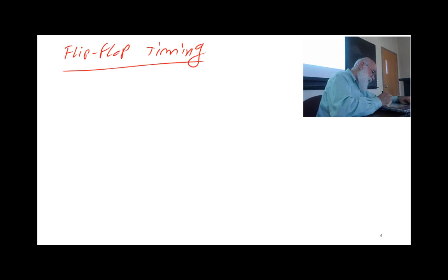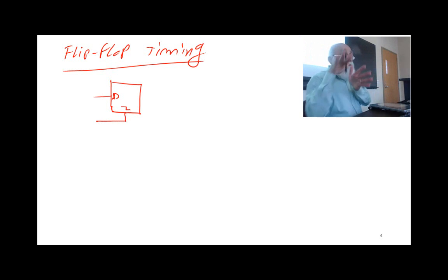when we talked about master-slave, it was the situation where whether you are doing D flip-flop or the JK or whatever you're doing, the clock is treated as if it's after the clock becomes 0. I don't say it's falling edge, I say after clock becomes 0.